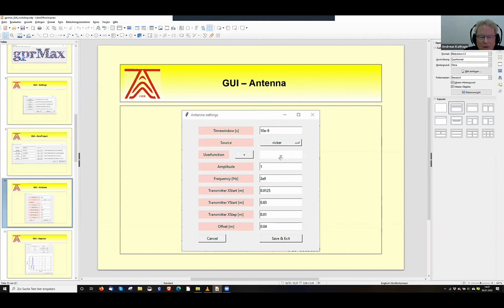And in this, you have also a function for smoothing and optimizing the function which you collected from a real radargram. As you will know, edges or jumps or any discontinuity would lead to unpredictable results. You need to have a smooth wavelet here.